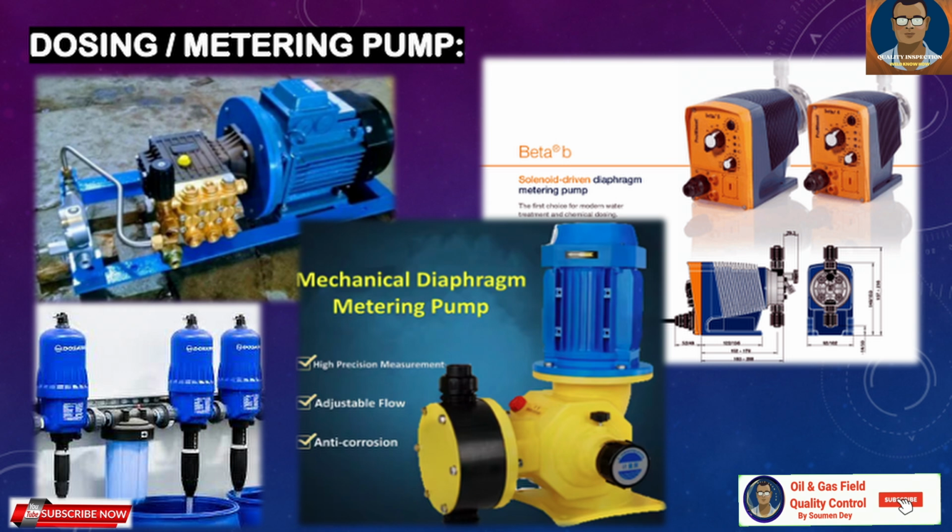Working principle: a dosing metering pump sucks a particular amount of liquid and feeds it to the pump chamber to add liquid into the process. The pump is controlled with an electrical motor or air actuator. It has a controller to switch the pump on and off, hence regulating the flow. Types of dosing pump available in the market: diaphragm metering pump, plunger metering pump, peristaltic metering pump, lobe pump, solenoid dosing pump, and multi-diaphragm dosing pump.